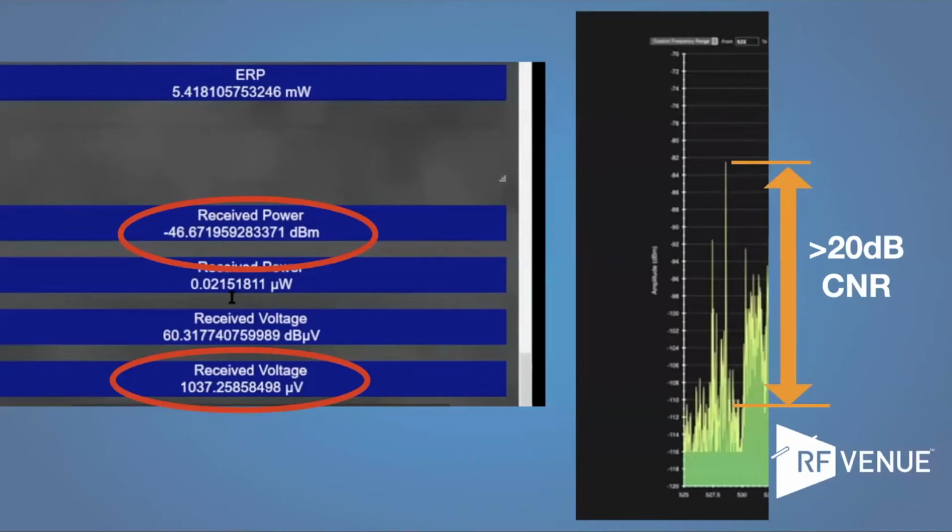Right. Well, if you measure you can avoid doing this. Probably a lot of you have never even considered a link budget and your system's working. Okay, it is. But this is going to give you a much better idea of where your limits are. So again, the thing that you have to shoot for is that you end up with a number that, and it depends how your scanner is set, is at least 20 dB above your noise floor.